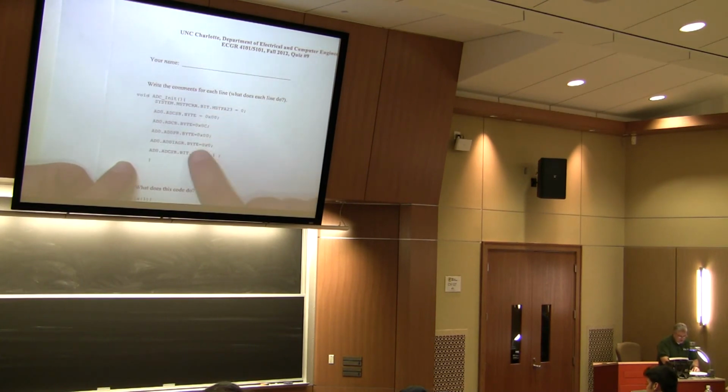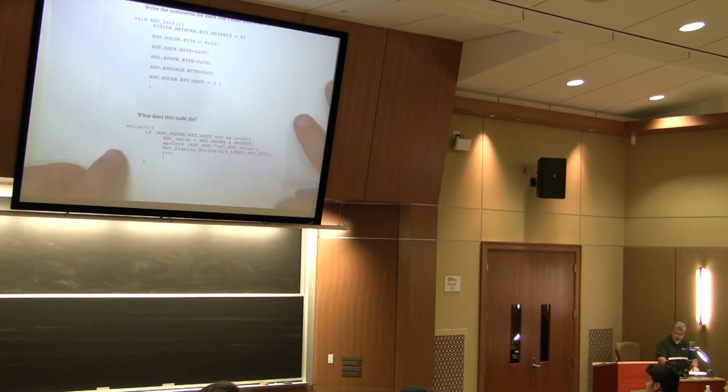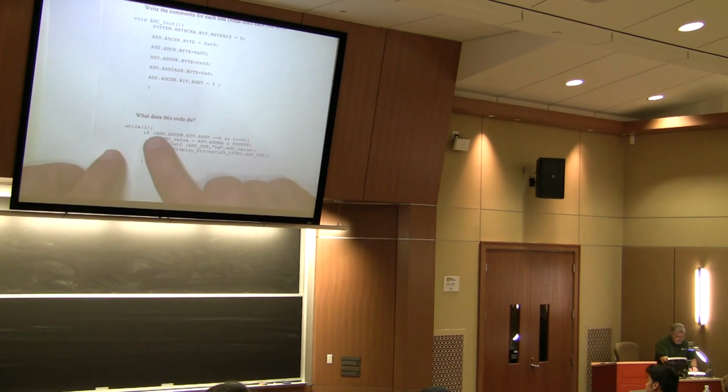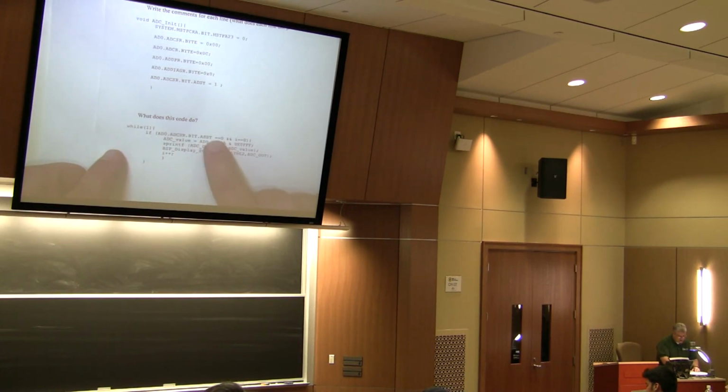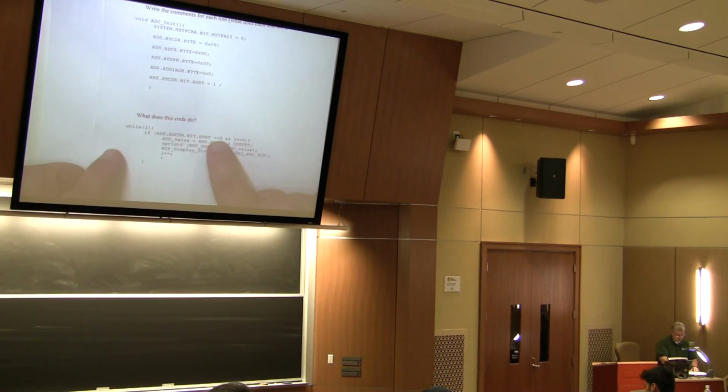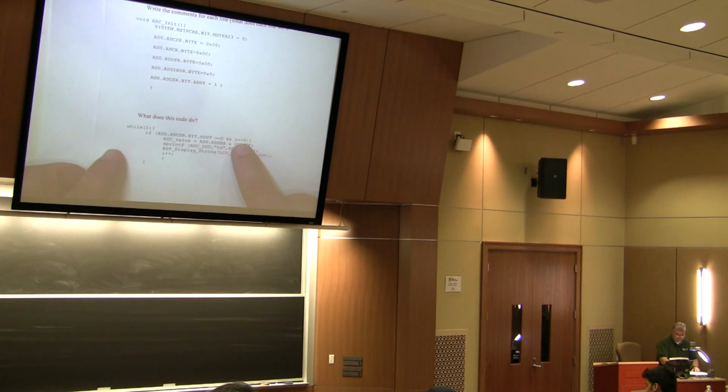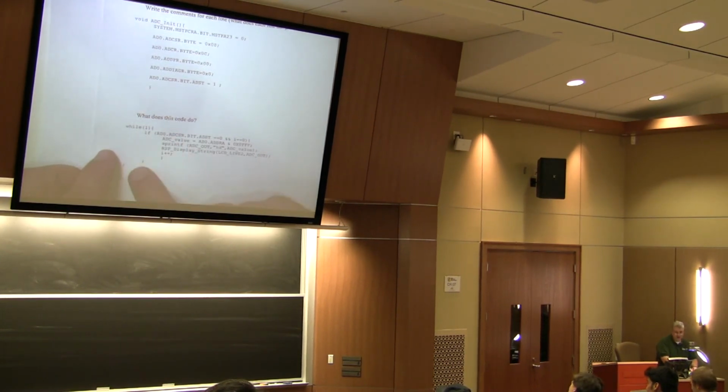So that means that we're setting up the registers that we will be using to read the ADC value, and then we start converting. And then perhaps right here, oh, look at this. If ADCSR bit ADST is equal to 0, so in other words, when it has done its conversion at once, it will set that bit to 0. And so when you see it, and I is equal to 0, then it's going to go through and it's going to read the value, output it, I++. It's going to increment. So what does that mean, I++? All right, so it adds 1 to I, which means that this code will only run once.